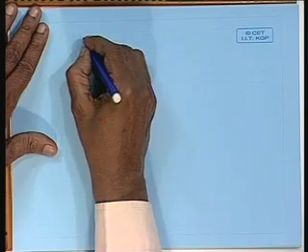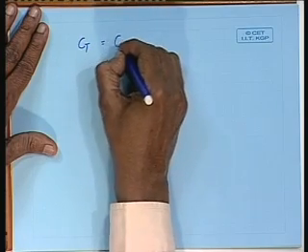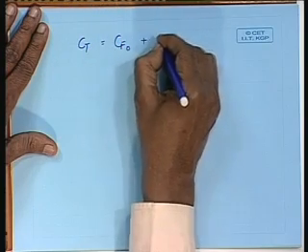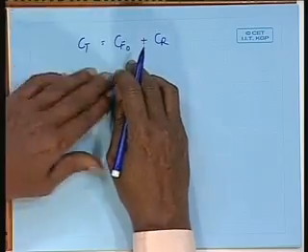We have seen that Ct is equal to Cf0 plus Cr, where Cf0 we have said is the ITTC based frictional resistance coefficient, which is primarily the 2-dimensional frictional resistance coefficient, right.